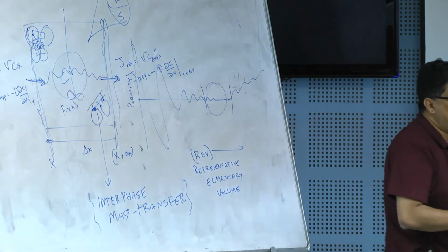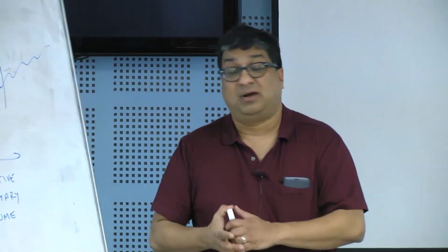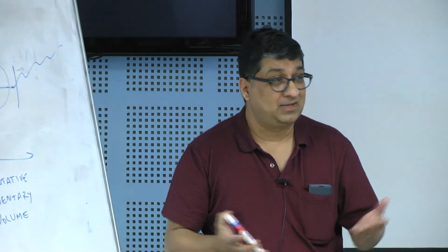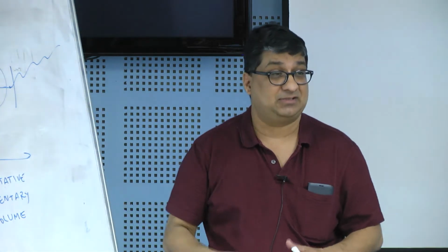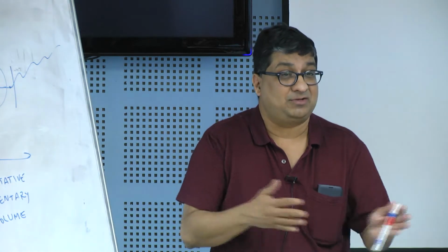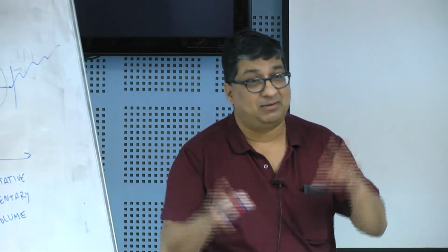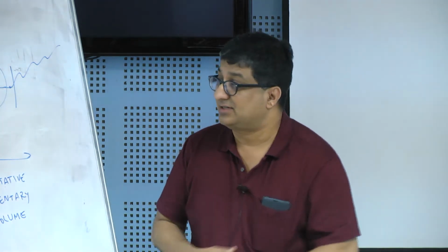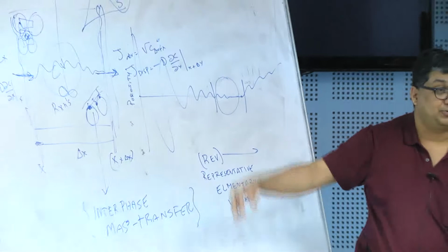And our system has two phases, solid phase and water phase. Okay. Because there is solid phase and water phase, our chemicals can actually partition or go from solid phase to liquid phase, to water phase. Reactions are where the chemical gets transformed from A to B. Okay. So just like with transport, these are what are called fate processes, because they are not causing the chemical to move, but they do decide the eventual concentration or the fate of that contaminant. So, when we talk about fate and transport of contaminants, the reactions and mass transfer are your fate processes, and then advection and dispersion are your transport processes.